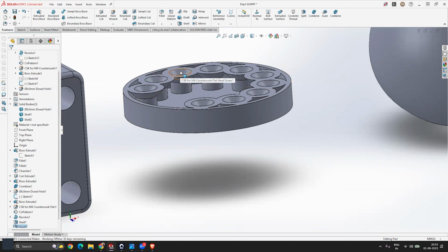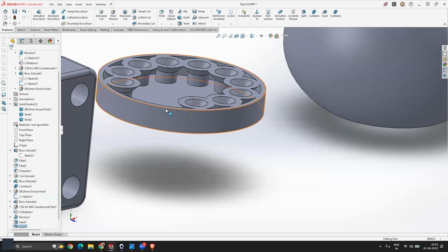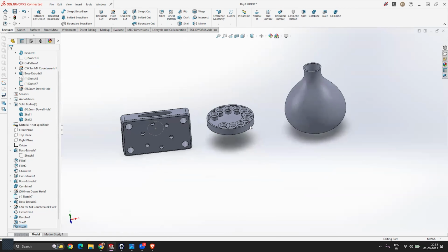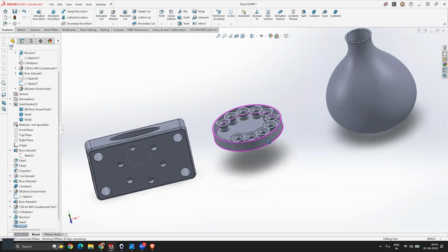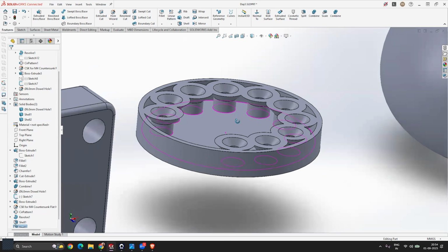If you're designing something for injection molding, and you want to maintain a continuous thickness around your complete plastic body, just to avoid any shrinkage during the plastic injection process, you can use this shell tool to maintain an even thickness around your complete design. So that is also possible. Now you can see it was very simple, very easy to use, and also looks very nice.